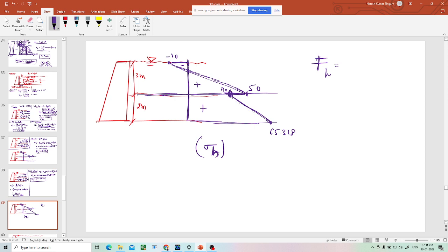See, we were discussing which direction the earth pressures were in. Earth pressures will be towards the wall, so they will push the wall. That is the pressure which is coming. So if you see, up to here it is positive, which means the wall is pushed. But at the top place, if you see, that place is pushed in this direction. Ideally it's not really pushed, it is pulling in this way.